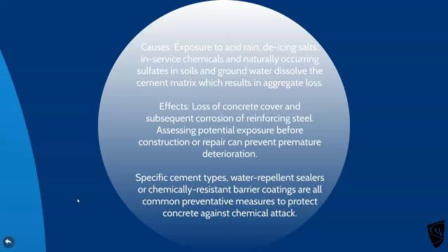Trying to assess the exposure before construction is important, because it means you can avoid having to repair later on. Make sure you use specific cement types, so ones that are water repellent, or you can put sealers on them, chemical resistance. So it's all to stop chemical attack.